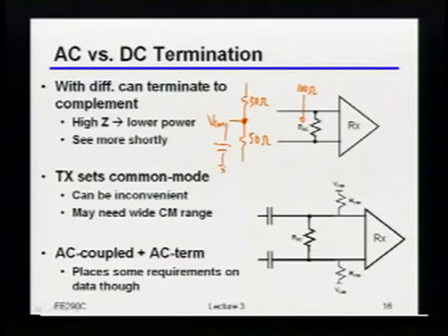Obviously, at lower frequencies, it's not really common mode terminated, but hopefully, down in those frequencies, you don't care all that much because there shouldn't be a whole lot of reflections going on in any case. So indeed, that's typically how you construct something like this. What's the typical frequency corner you put over there? Oh, that varies pretty widely. It could be anywhere from, let's say, 10 up to a couple hundred megahertz or so. For 50 ohms at 10 megahertz, you need a huge cap over there. It is indeed big. But that's life. Not much you can do about that.